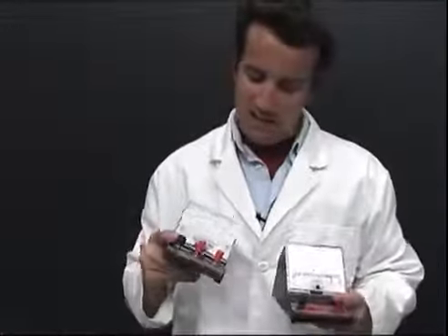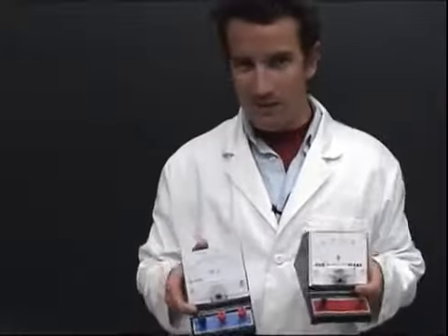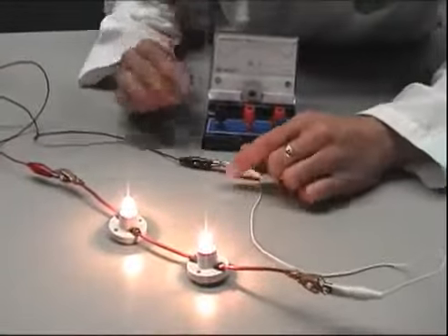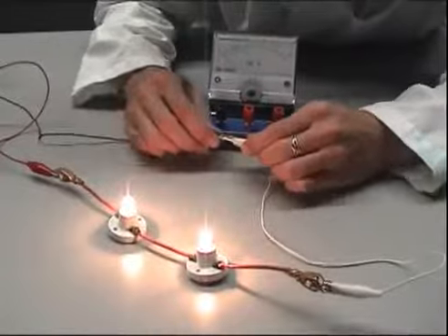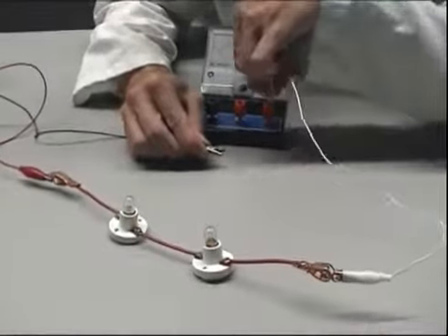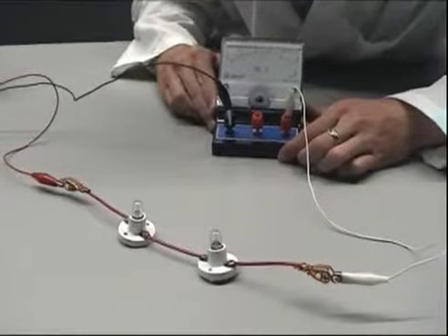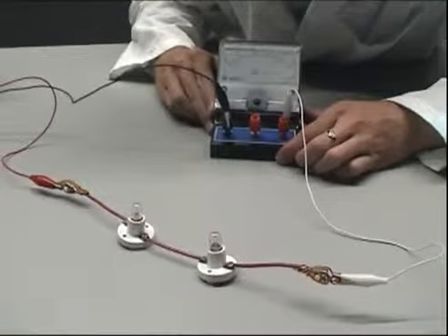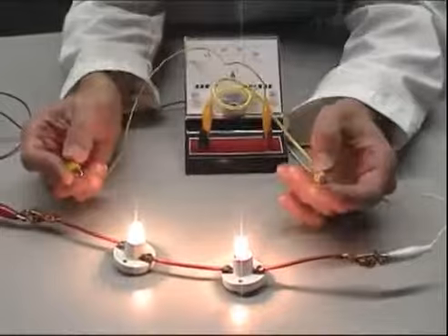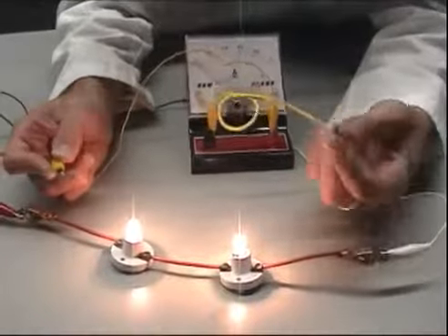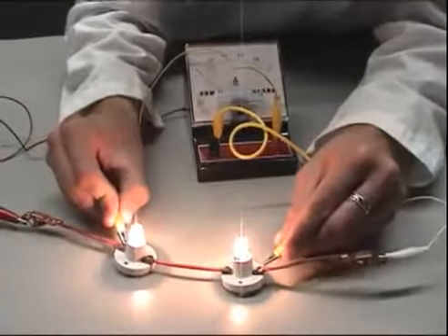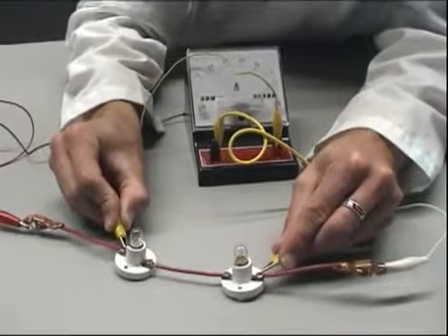Now, if you were to hook up these probes the wrong way, what would happen? Here is the voltmeter being added to the circuit incorrectly in series. The circuit fails. Here's the ammeter being hooked to the circuit incorrectly in parallel. The circuit fails.